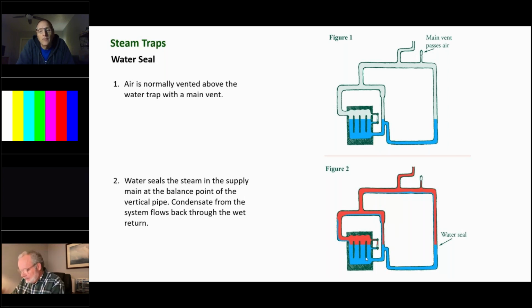So the two big things with a new steam boiler installation, one would be to find some way to flush out or visually inspect that wet return. And the other, which is more recent, is putting some type of filter on your city water. Again, this is Cincinnati. It may be different where you are.